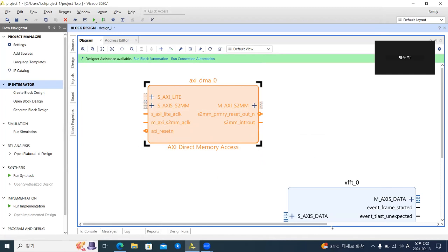If you look at the name of the wires in details, you will see AXIS with an SAXIS and an NAXIS. They each correspond to a master and a slave. In an interconnect, a single master will be connected to a slave. The master's responsibility is to say, hey, I will send the data now. And right after, the slave will respond, okay, I'm prepared to get some data. And then the master will be actually sending the data. This is called a handshake and how interconnects work at a very basic level.